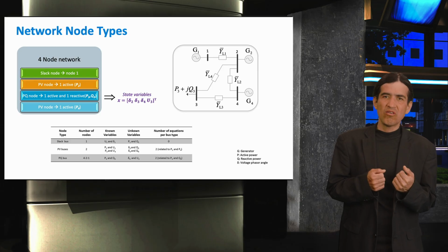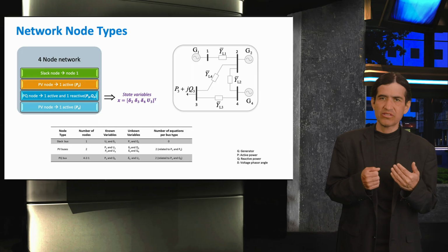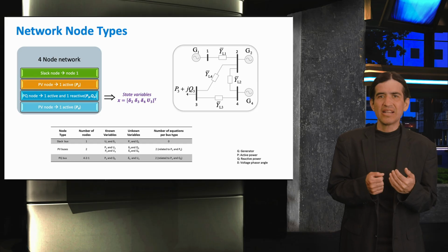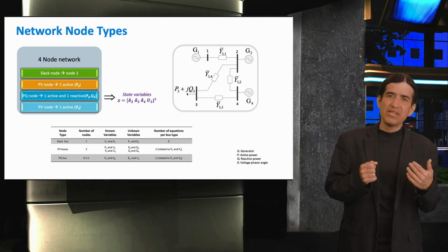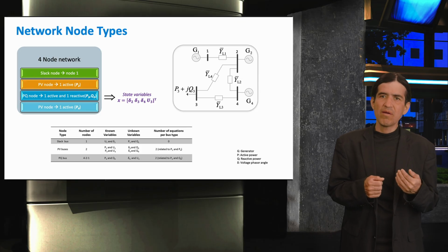The outcome of power flow calculation concerns the value of the voltage phasor magnitude associated with bus 3 and the voltage phasor angles of buses 2, 3, and 4. The unknown active and reactive power injections can be determined from these outcomes and the relevant elements from the Y-bus matrix.